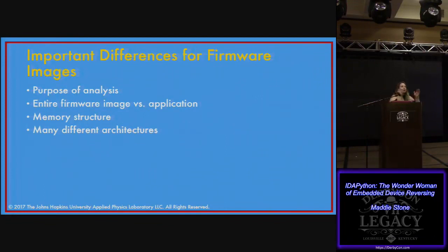So that's where we want to focus our analysis: what are they sensing, what is the data coming in that they're making decision points off of, and then how are they making the decisions that go out. So that might be turn on this motor driver, turn on these lights, add power to this system. So that's what we want to use scripts to focus all of our analysis on. We also care about how they are configuring and controlling peripherals or their communications interfaces, what's coming in and going out via serial, CAN bus, etc. Are they using compare captures or PWM modules?